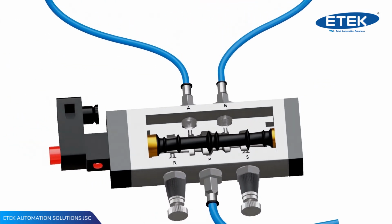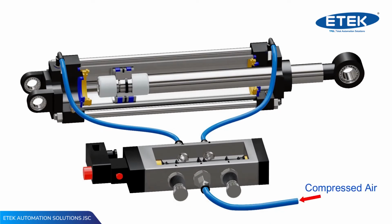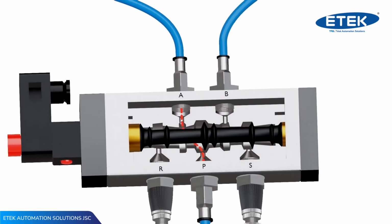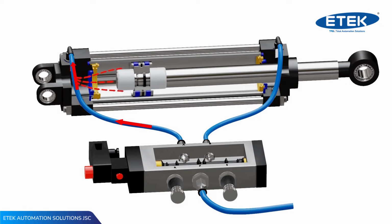Now let's understand how a pneumatic cylinder works. The compressed air is supplied through inlet port P of the valve. The valve directs air in a particular direction, which we can observe in the animation. In this case, the air is directed to port A. This high pressure gas is then transferred to the cap end of the cylinder through the pneumatic hose. This creates high pressure in the cap end of the cylinder, which therefore pushes the piston towards the head end.